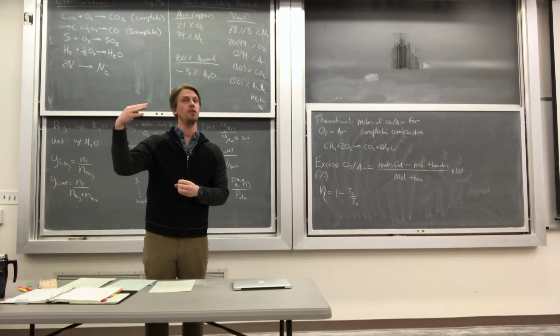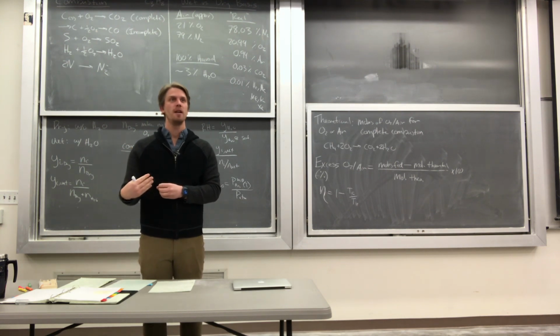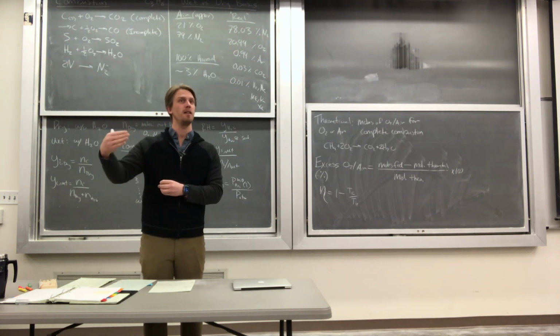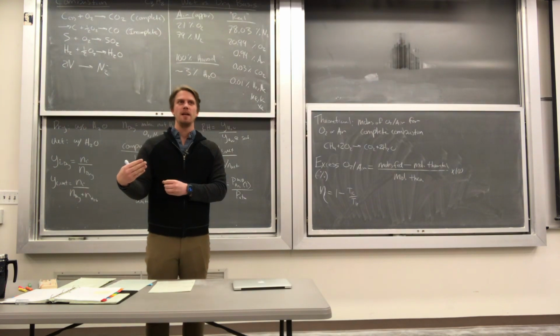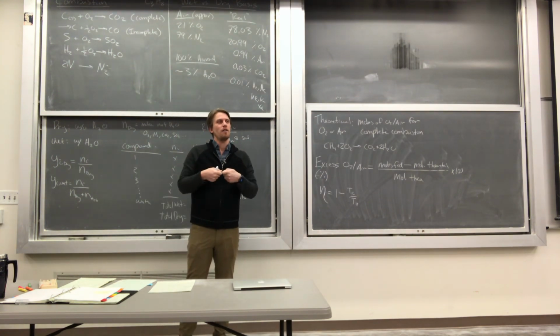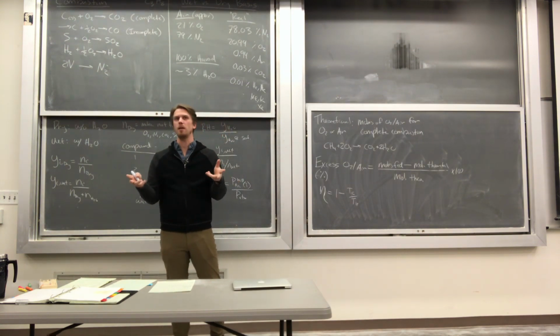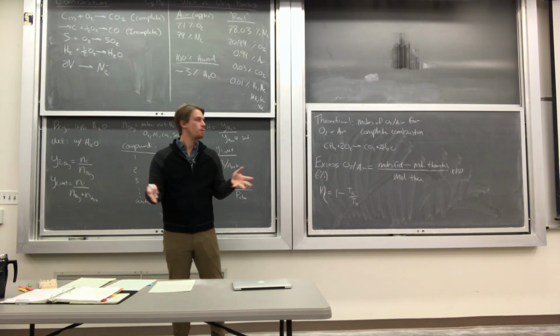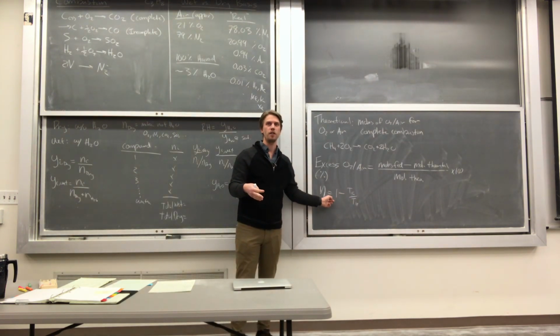Right? We only actually learned of this in about the late 1800s and early 1900s. Right? So Maxwell-Boltzmann and the kinetic theory of gases is where we got the physical understanding for why temperature is the velocity. Now, if I have to break that chemical bond, and now I have to give that energy to 5 times as many molecules, each of them speeds up a little bit less, which means that my burner is now at a lower temperature, which means that my efficiency of the process is going to go lower.